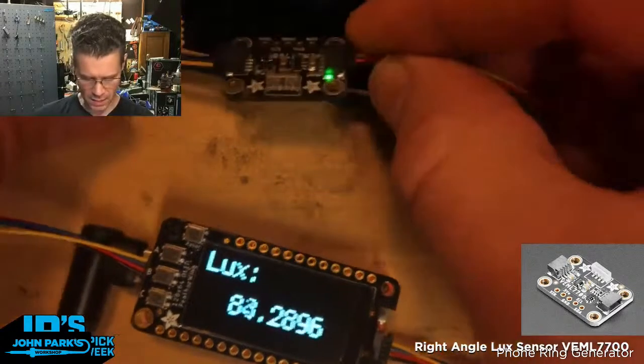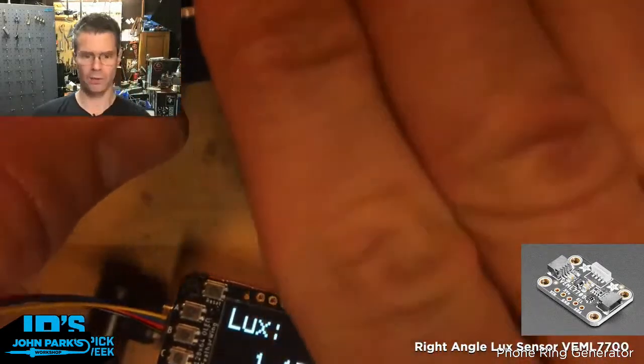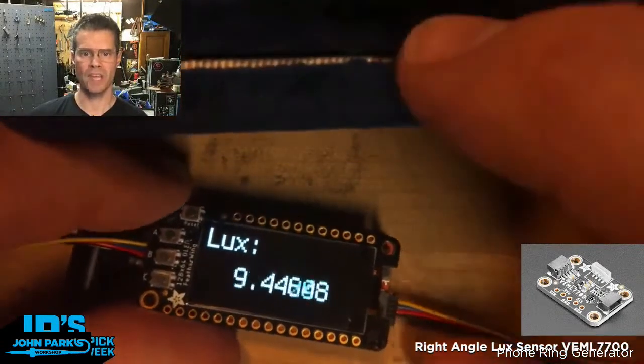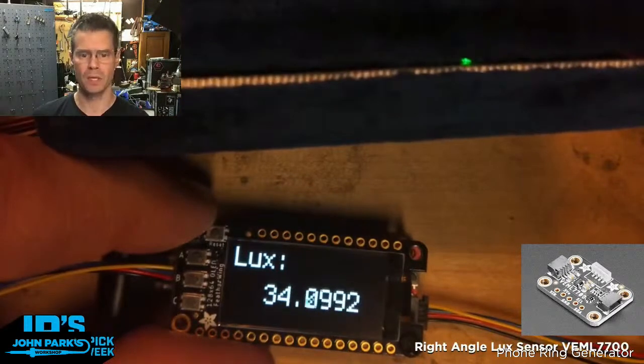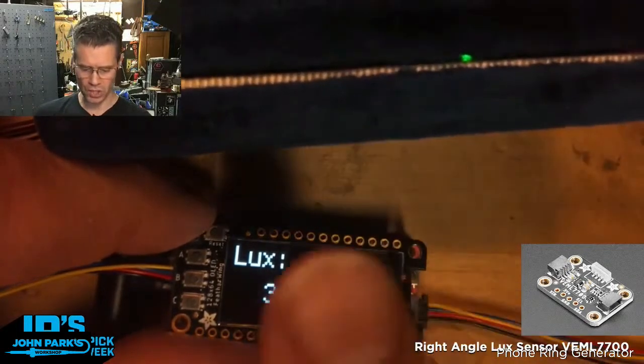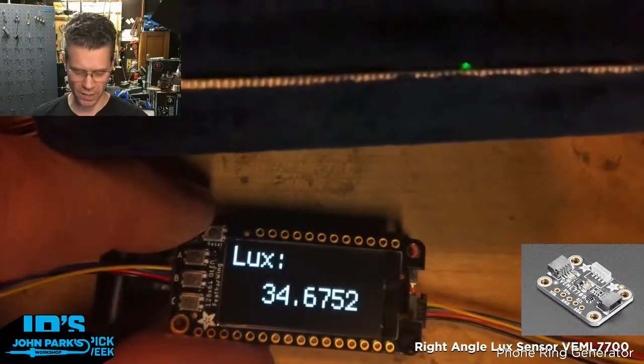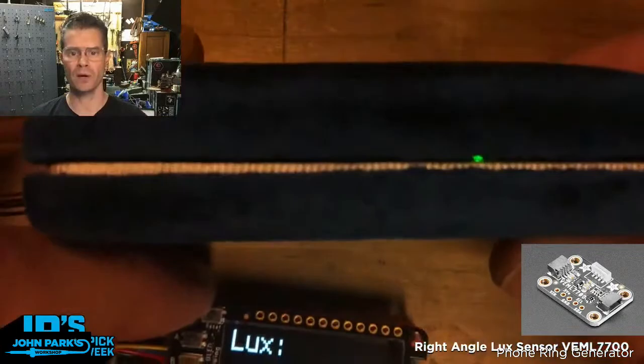It is the right angle lux sensor, VEML7700 with Stemma QT. This one has the sensor mounted parallel to the board instead of perpendicular to the board, which means you can fit this in some tiny little areas. Since this is mounted at this angle, I should be able to stick this inside of my little box here, and you'll notice it's just peeking out right there. You can disable that LED, by the way. So it's just peeking out there, and we're getting, just from my ambient lighting in the room, about 35 lux. And as I put my hand over that, it gets pretty dark, down to 1. So you could use this for detecting objects, particularly for things like security things, puzzles, escape room stuff. I always like things like that, magic tricks, if you want to have it mounted fairly discreetly. The right angle lux sensor with Stemma QT.